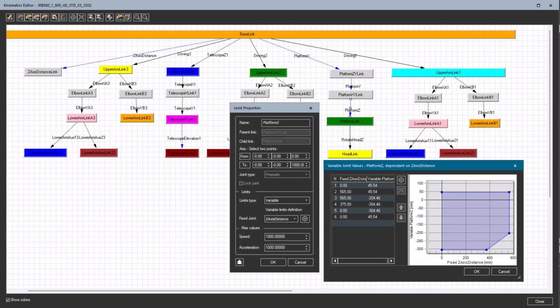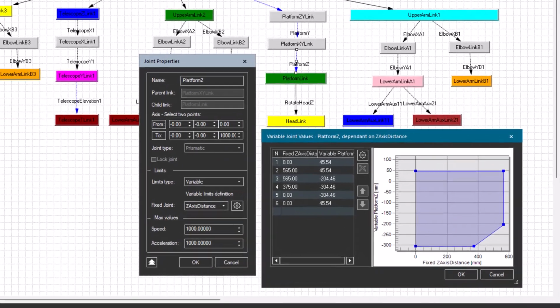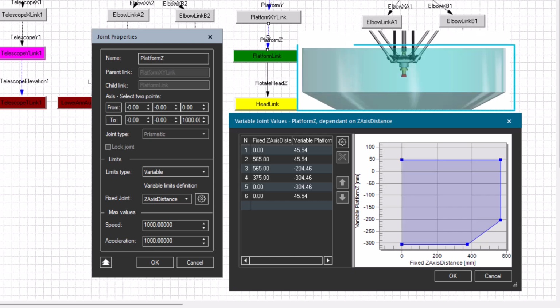This describes the extremities of the reach envelope. In other words, the furthest points the robot can reach. Let's display the reach envelope above this graph. Note the graph displays 1/2 of the reach envelope because the envelope is defined by its radius. The origin of the graph corresponds to the robot's tool frame.